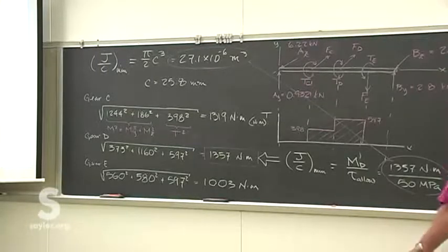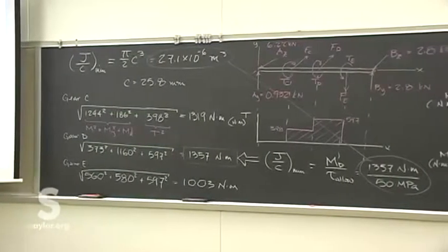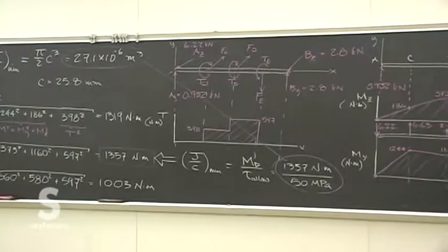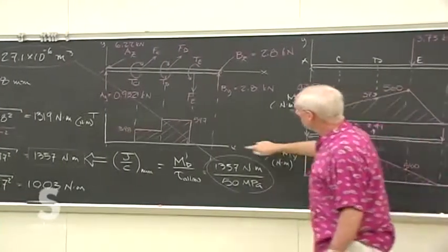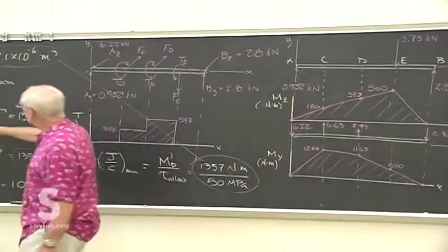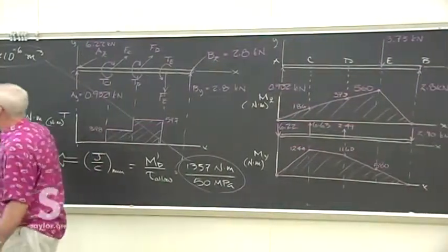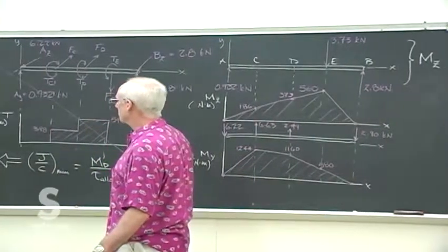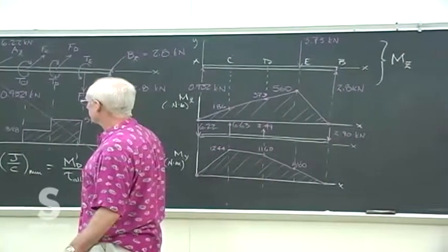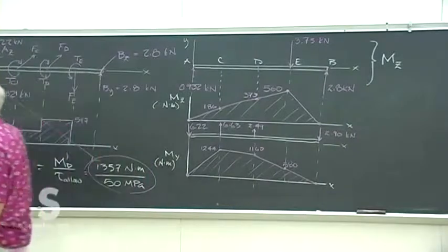Before I clean up, any questions? So we'll just take the two different 2D views, figure out what the moment diagrams for there are, and then add the torsion, and then at each place figure out what those three do to combine the internal forces of the shaft. And C gives us radius.